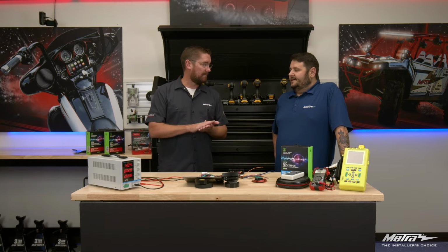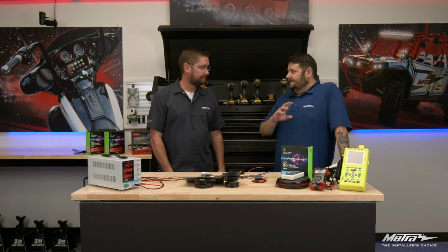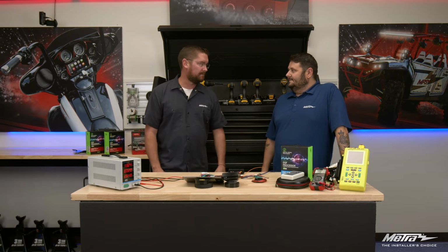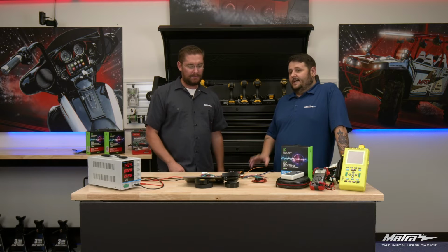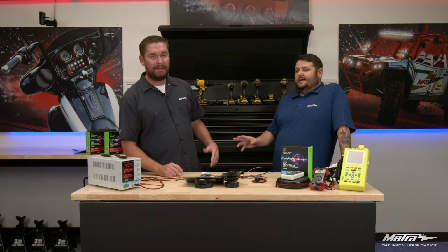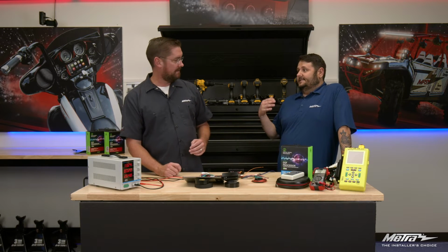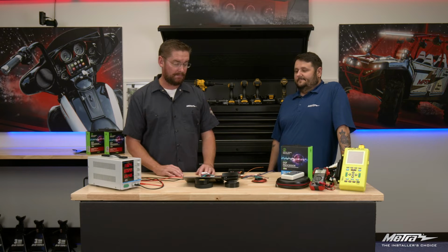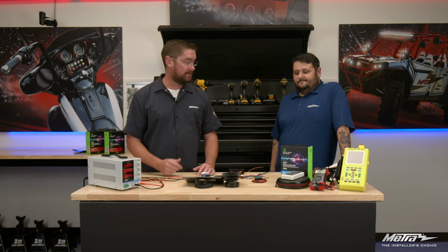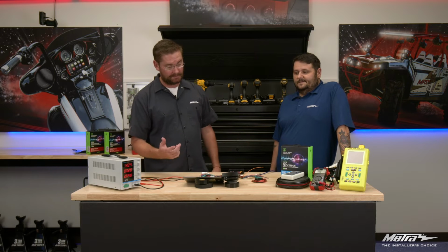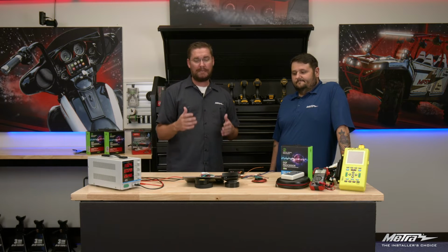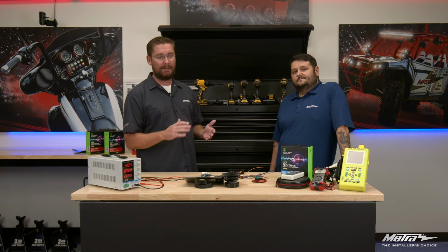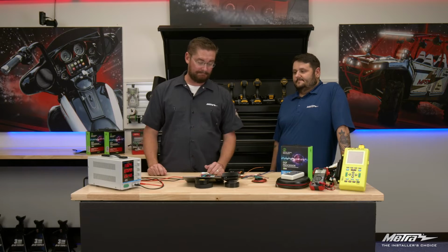There are a lot of guys that have tuned it out. I think it's 233 megahertz or something like that. I think it's like 8,000 hertz, but yeah, something like that. They found it and tried to tune it out as best they can, and even then it's still not perfect. You lose some quality of the music if you end up cutting out frequencies that aren't supposed to be cut out, all because of a chime. So our DSP is going to take care of that for you, and it's going to allow you to set that chime level exactly where it needs to be.